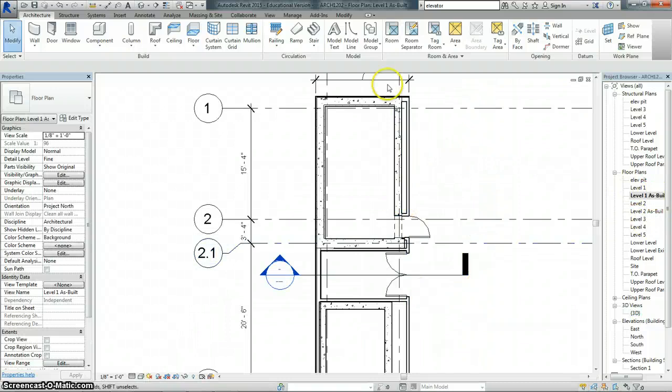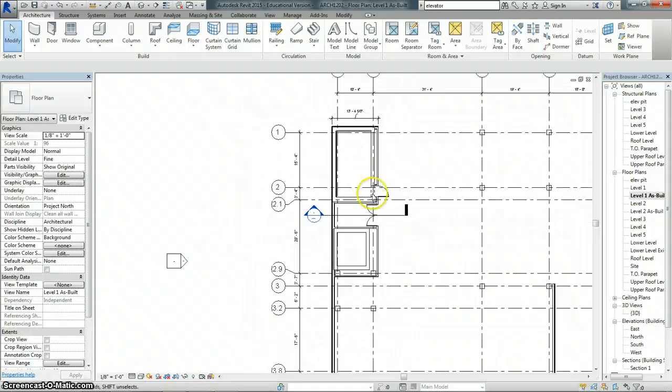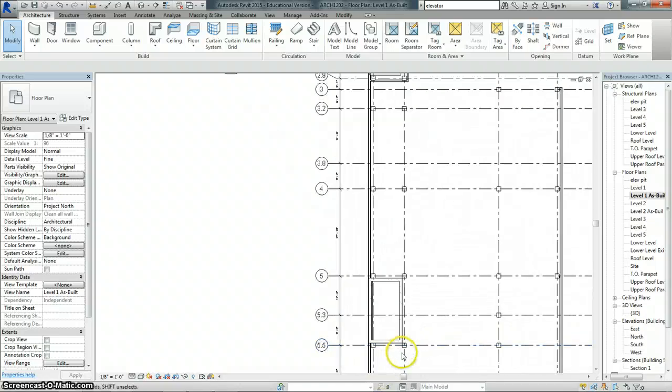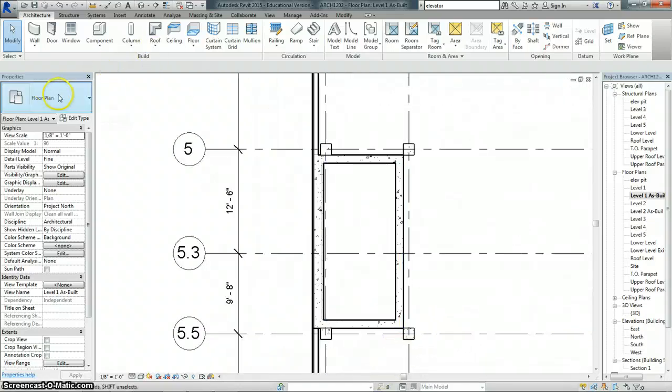So that's how easy it is to place doors. As you're going through your hallways and on the exterior and placing doors, it will be that easy. I've been just using the flush doors, unless there is a glass door, which there are a few of those. I would just use something that's fairly simple to place in.